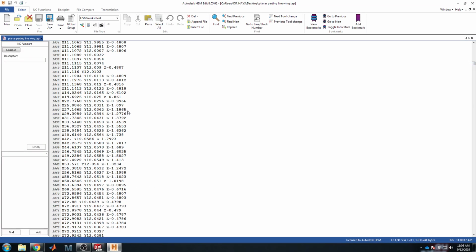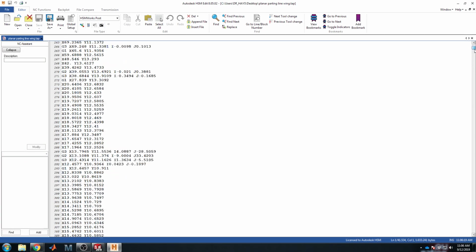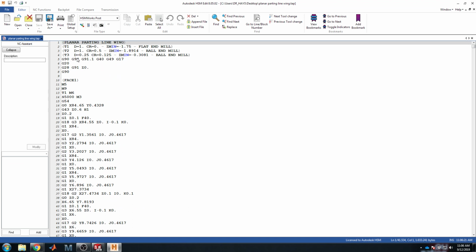These are XYZ coordinates. Lots of setup information here at first, and these are what are called Gcode files because everything's G90, G94, G91.1, G40. All of those commands mean something to the CNC machines. If you want to know what that code means, there's an excellent Wikipedia summary of all of those Gcodes. Different types of software understand different portions of the entire standardized Gcode.